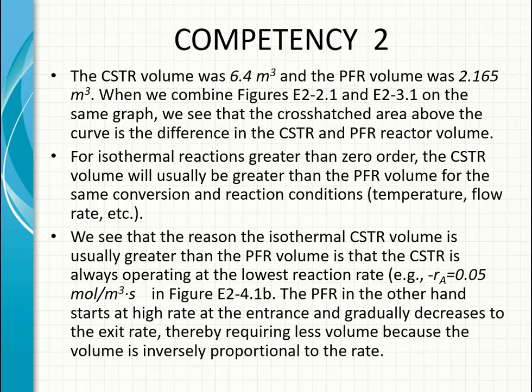In figure E2.4.1b, the PFR, on the other hand, starts at a high rate at the entrance and gradually decreases to the exit rate, thereby requiring less volume because the volume is inversely proportional to the rate.